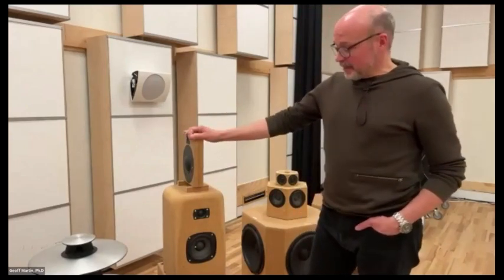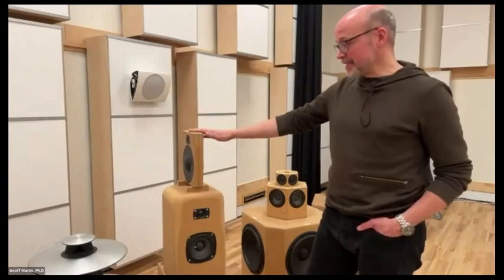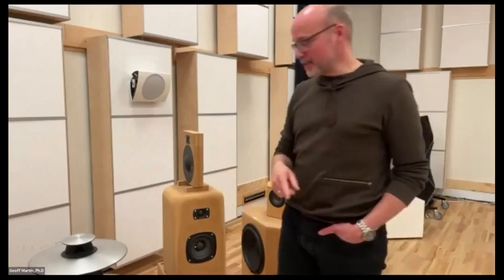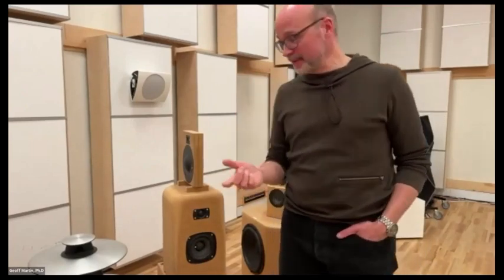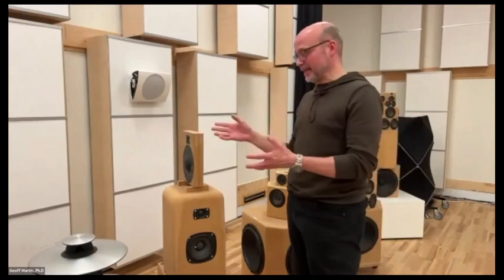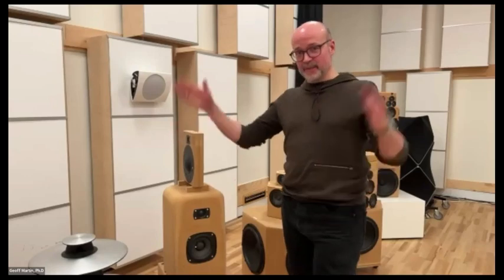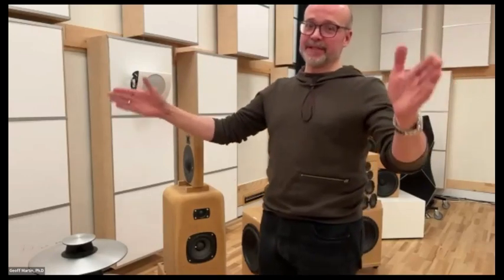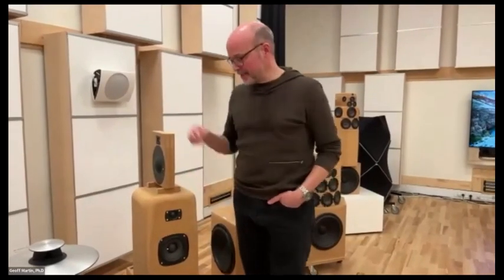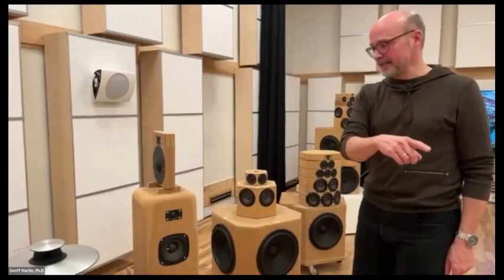However, in a real world, this thing sounds terrible. And the reason it sounds terrible is because we don't live in a free field with just the on-axis response, and we don't live in a diffuse field where this is actually filling up a power response and doing nothing else. Typically what happens with a pair of loudspeakers built like this is that you put them near sidewalls. And when you put them near sidewalls, you get an on-axis response from that part, nothing from here until it bounces off the sidewall and comes back.